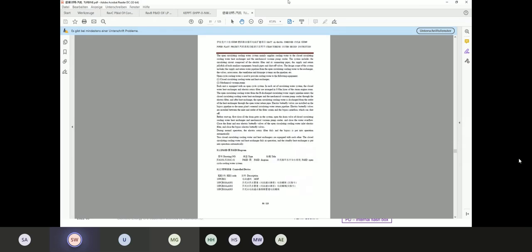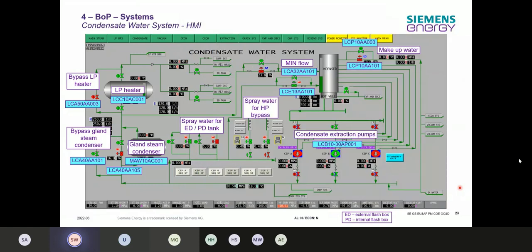But over here, like I said at the beginning, it's a Chinese boiler and water steam system. But when it's not in, I would for sure check it with the system, because there must be something in with level low. This must be in. So when you get a level low from the hot well, at one point there must be a protection for the pumps.